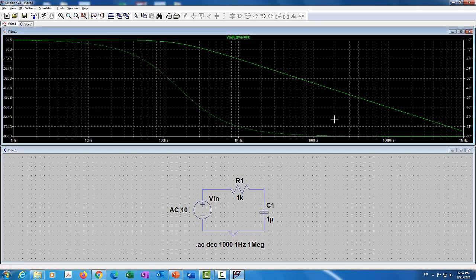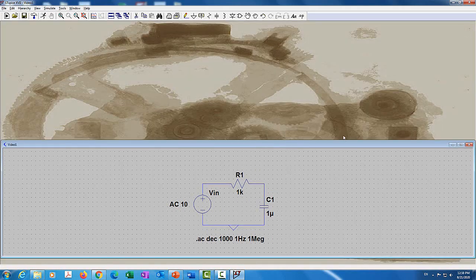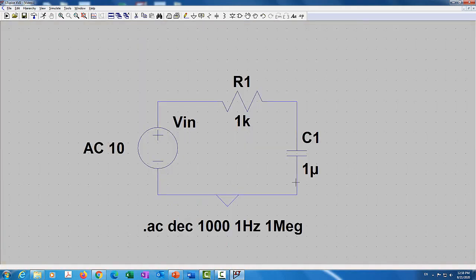And this is the first aspect of this circuit that we're going to do. Now what I want to do is relate to the step response of the first order RC circuit. So I'm going to basically delete this AC sweep, because we're going to use transient response. So I'm going to click on cut, select this here, and click on cut, delete this, and then I'll skip.